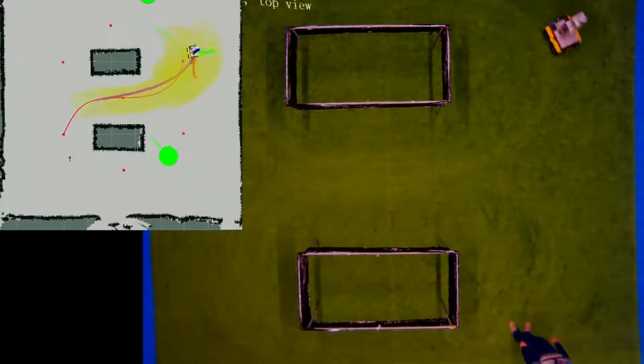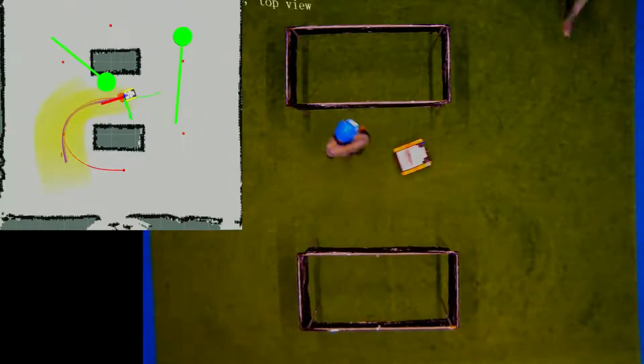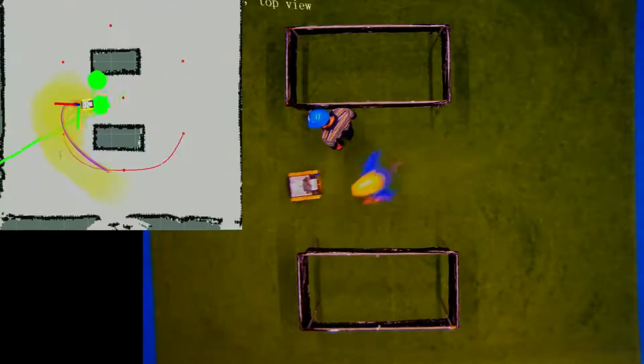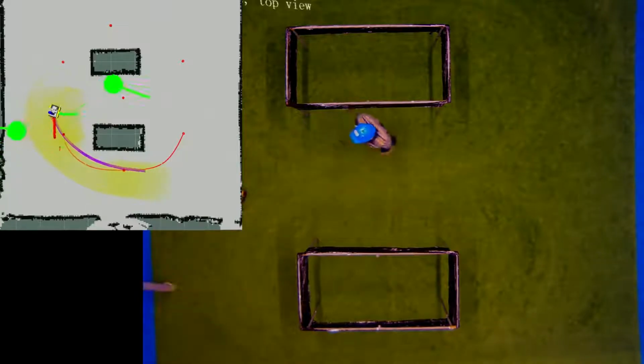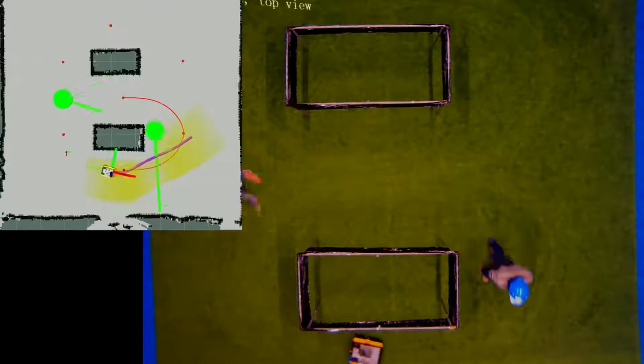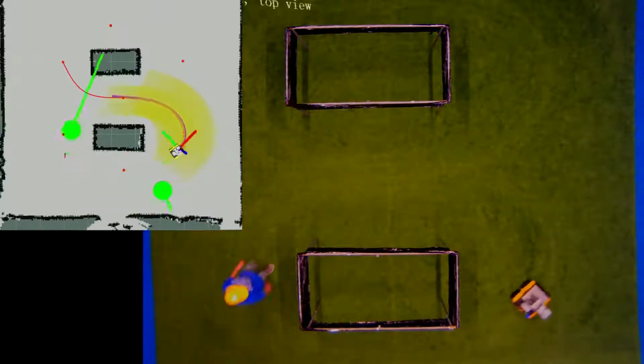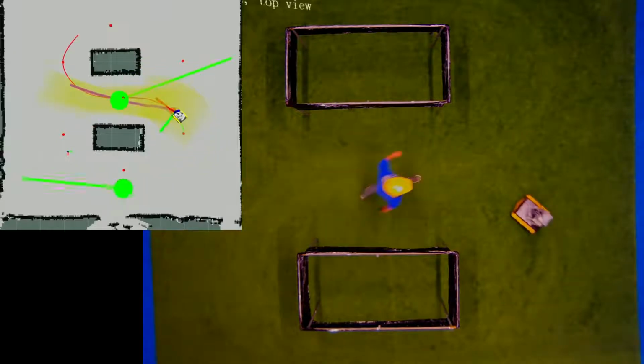In a closed dynamic environment, we tested planning performance of our method following a predefined path. The green circles in the visualization represent the interacting pedestrian, which are being tracked by a motion capture system. Using a linear velocity prediction, we can see that the planner is able to anticipate on the dynamic behavior and